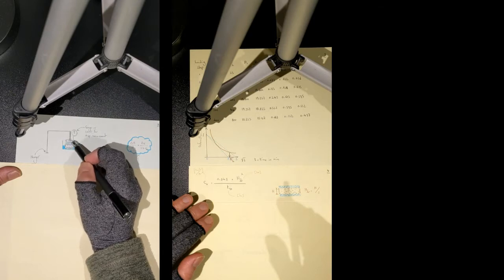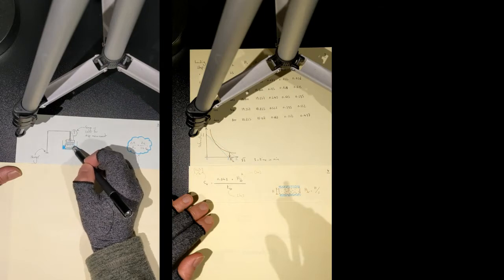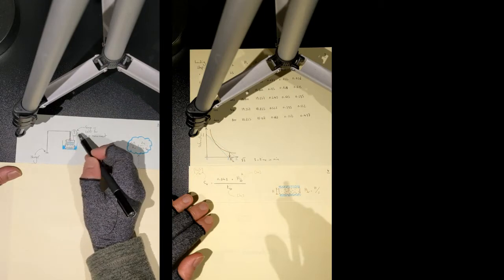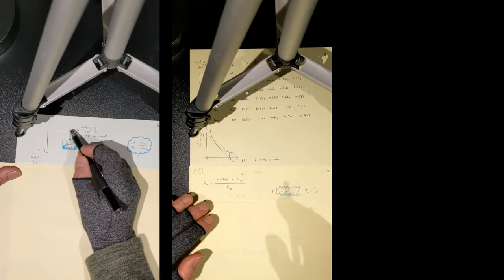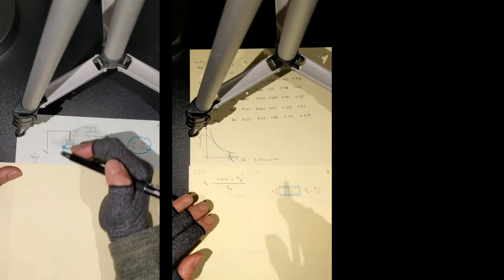And that is force, vertical force. If you divide your vertical force by the cross-sectional area of this circle, diameter square pi divided by 4, you can convert that force to pressure. Also, your loading cap is connected to either a digital or a mechanical gauge, and that gauge shows the degree to which the cap goes up or goes down during the course of the test. So it can measure the heaving or swelling or settlement, subsidence, or even collapse.